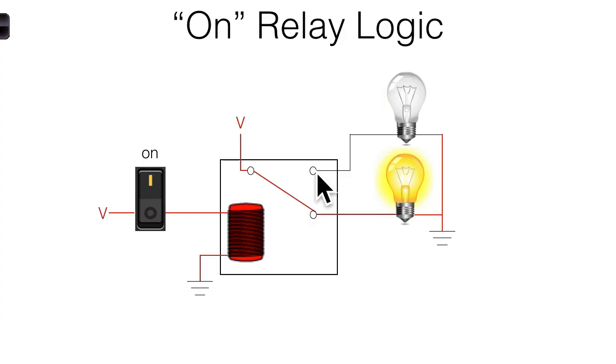If you can imagine these all chained together in different configurations, some were in series, some were in parallel. If you start thinking about those series, what is that? I need this one. If this switch is on and this switch is on, then power would flow through and it would turn on the light, the motor, whatever was downstream. If I had it in parallel, what would happen? Think about it. What would happen? It would say this switch is on or that switch is on. So either one, and then it would continue downstream.